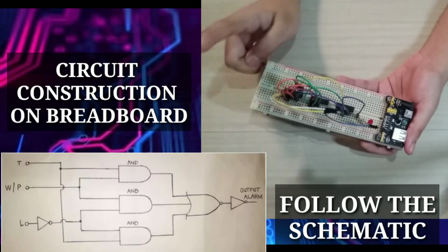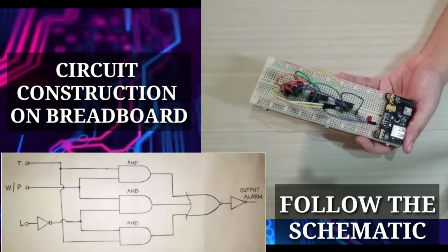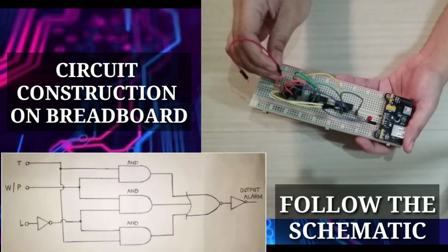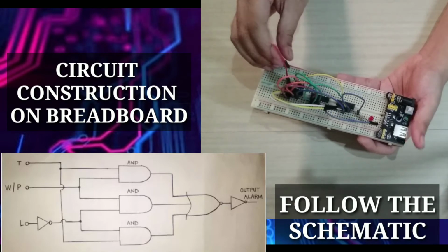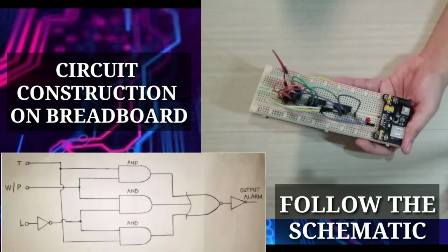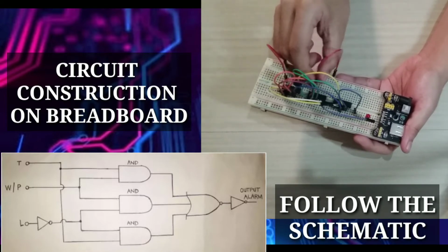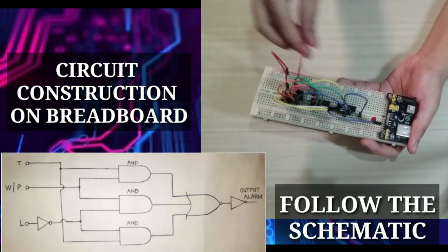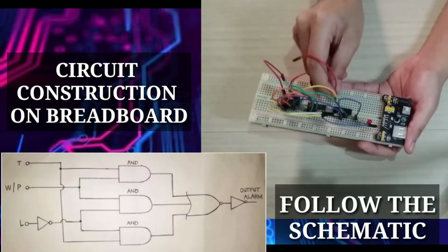Now, do not forget the most important part of our circuit, which is the connection of our integrated circuits to our VCC supply. So let's connect all of the integrated circuits to the voltage supply. It's on the 14th pin, the VCC connection of our ICs.